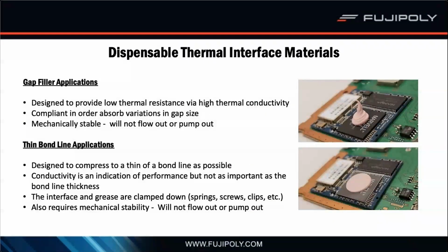So with any thermal interface application, we suggest identifying and understanding the type of thermal interface you're working with. As mentioned, it's really important to understand whether you're dealing with a gap or whether you just need to break down the contact resistance. So the first type of dispensable TIM application is the dispensable gap filler. Here you've got an actual physical or controlled gap with some sort of tolerance. These gaps have to be controlled. In other words, there has to be a spacer or some sort of hard stop in the assembly that's going to help set that gap. In these applications, there typically isn't a lot of clamping force, so any stress that's created is caused by the gap filler as it's being compressed and deformed.